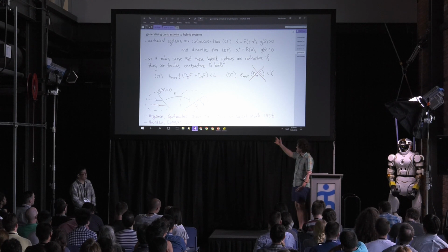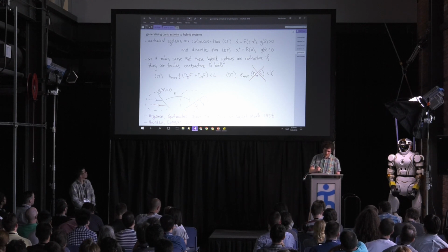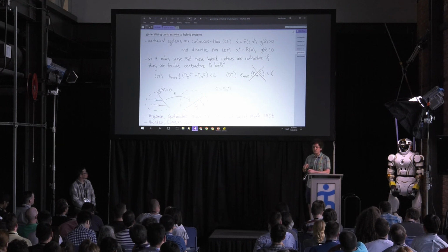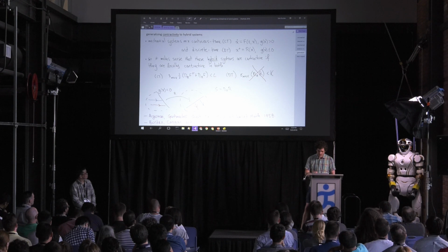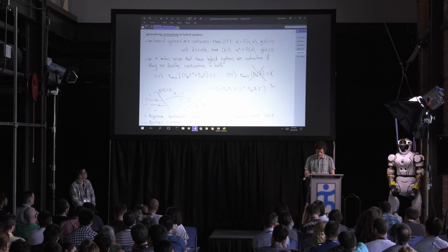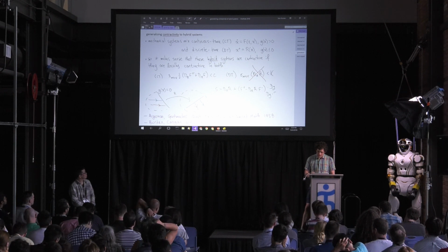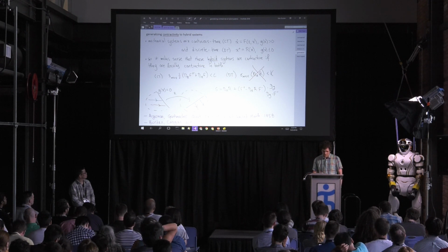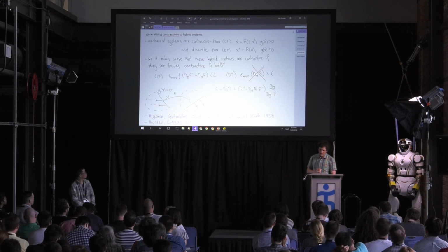So this picture doesn't exactly explain it, but really what you need to do is look at what's called a saltation matrix, something that takes into account not only the discrete reset that you're going to get from that map, and the first order effect of that, but also the difference in the vector field immediately after and the vector field immediately before, properly stitched together through your reset map in the direction of your surface normal to your guard, this dg there.